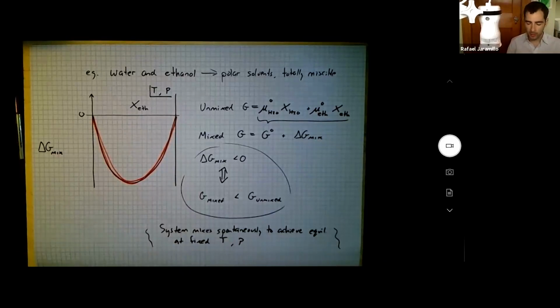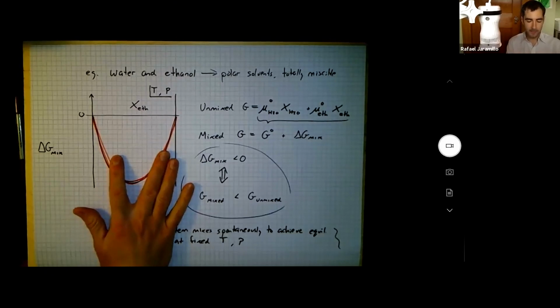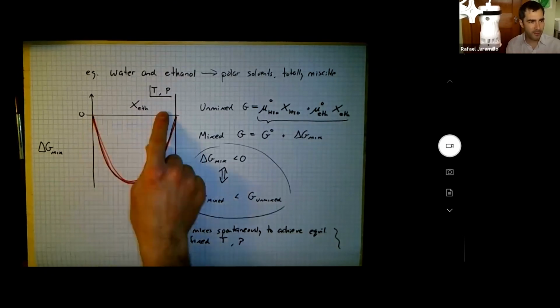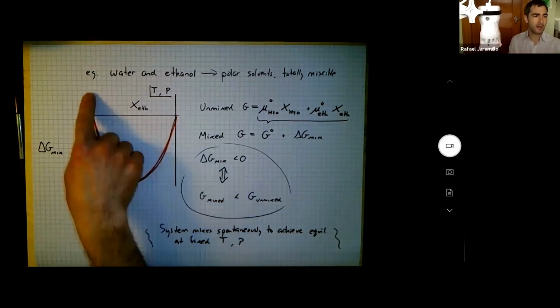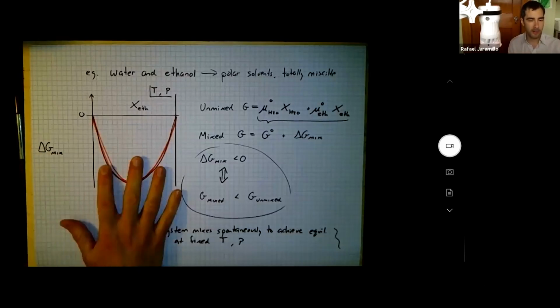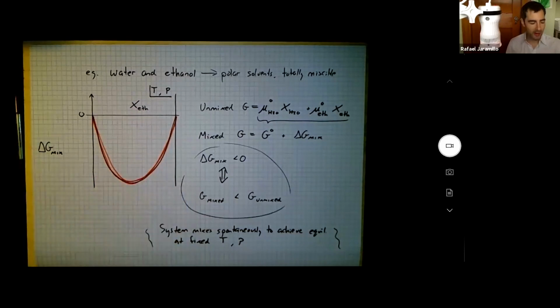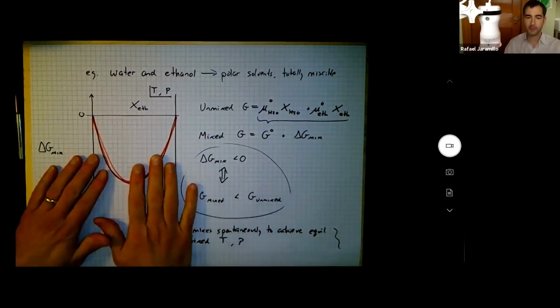Okay, so this sort of plot here is not a phase diagram. That's a variable you find in a phase diagram, but that Gibbs free energy is not found in a phase diagram. This is called a free energy composition diagram. And you will be very, very tired of free energy composition diagrams by the end of the semester. But anyway, that's what it is. It's called the free energy composition diagram.